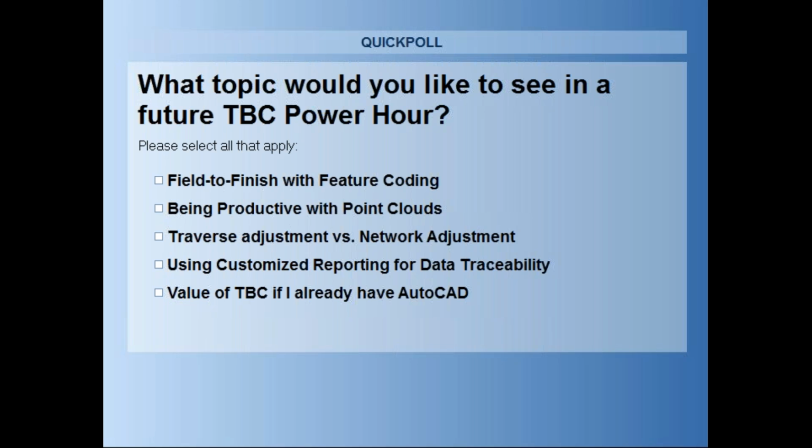Definitely. Another question that Laura asked, or not really asked, but a statement, was that I made the comment before that TBC does support alphanumeric points, but Civil 3D does not, and that is true, Laura. Civil 3D does not support alphanumeric points, so that's important if you're sending this data to that end package. It's important that you know that as well.